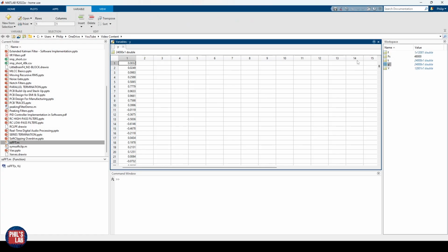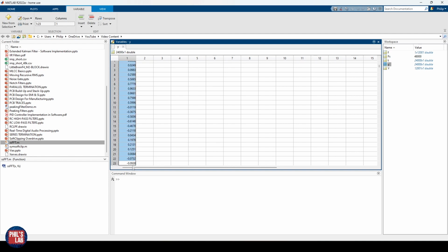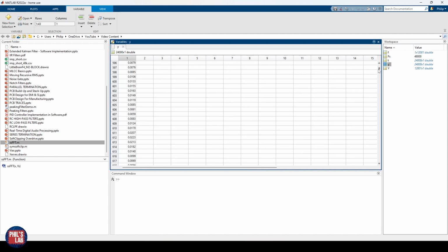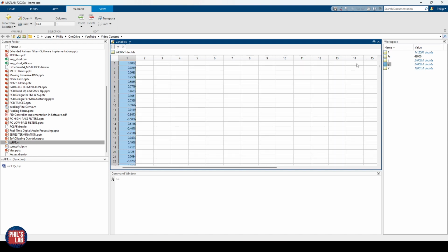The nice thing is then, this array is simply the time domain information which you got from our WAV file, which is effectively comma separated values. So we have floating point values at every sample index, and the sample index, of course, is based on our sampling frequency, so every sample will have a different value. And these values then build our FIR filter kernel. So we can pretty much just take these values over into our software, create a FIR filter structure, and then compute the output. And that's it. That would be our impulse response loader.